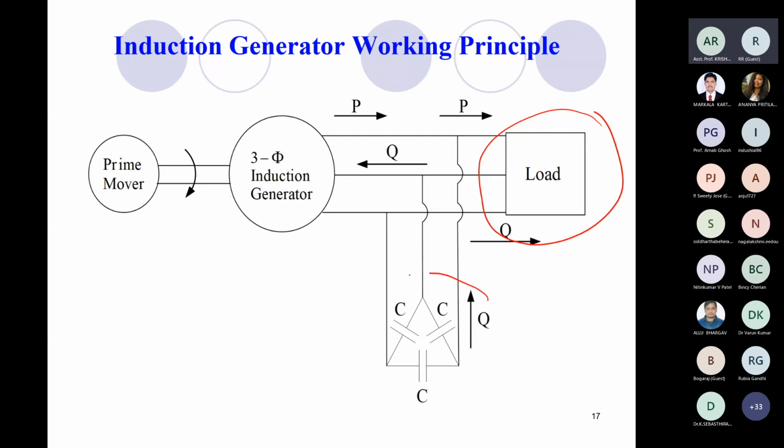Okay, so these are the capacitors, connected to the induction generator terminals, that is stator terminals. This capacitor will supply the required reactive power.